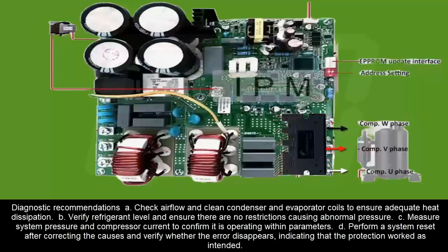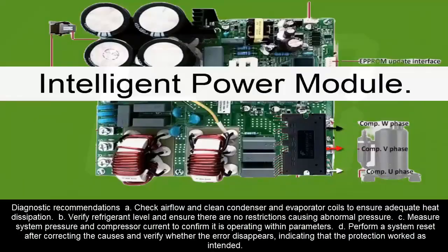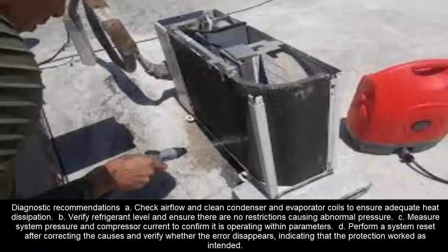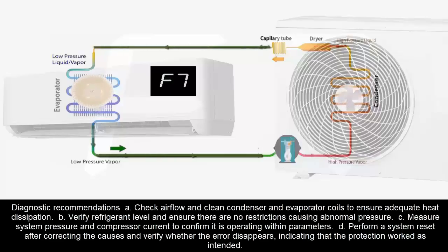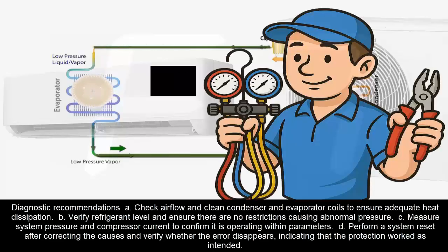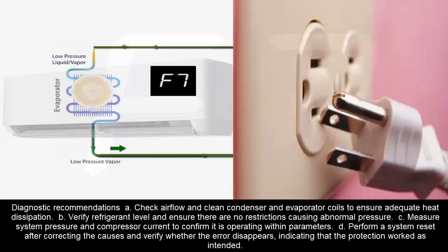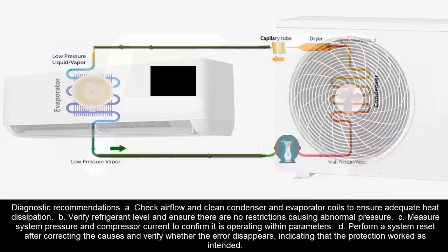Diagnostic recommendations. A. Check airflow and clean condenser and evaporator coils to ensure adequate heat dissipation. B. Verify refrigerant level and ensure there are no restrictions causing abnormal pressure. C. Measure system pressure and compressor current to confirm it is operating within parameters. D. Perform a system reset after correcting the causes and verify whether the error disappears, indicating that the protection worked as intended.